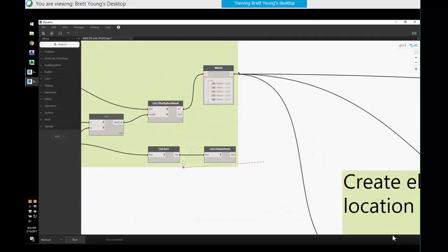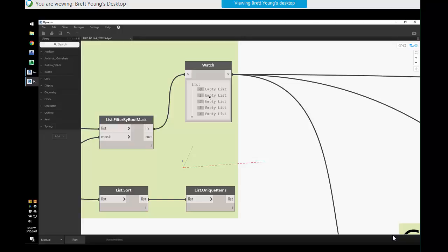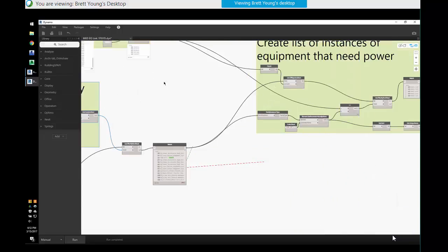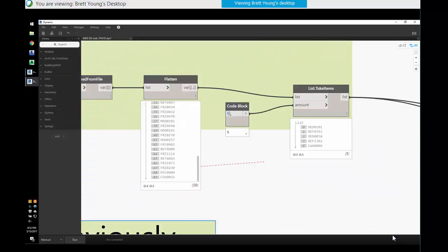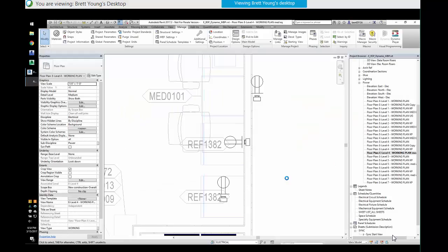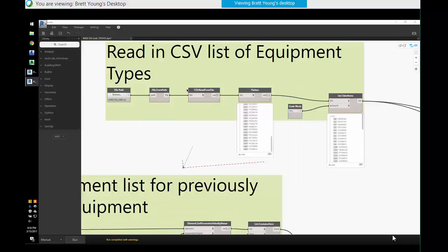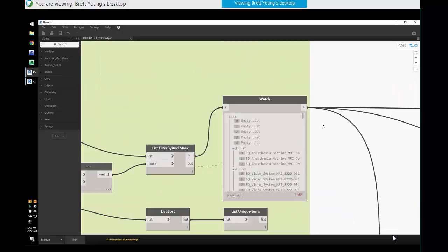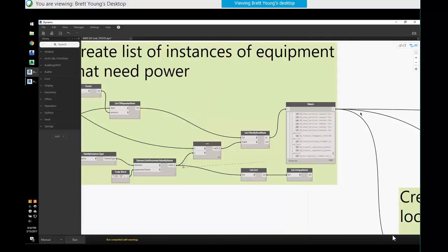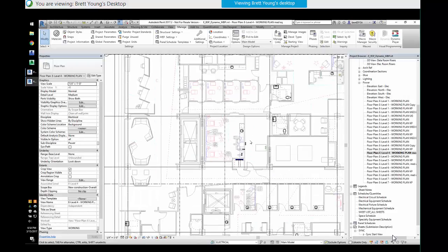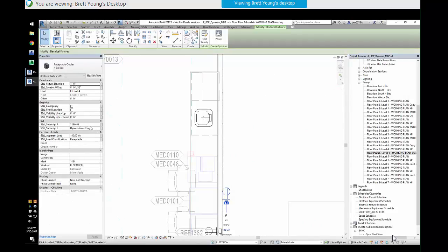So at the end of the day, I didn't put any more receptacles in round 2 because those first 5 pieces of equipment are already placed. So if I go from 5 pieces of equipment to 50, the full list, it's going to run. The first 5 are already placed, but you can run this every day to make sure that your receptacles are always matched up with a piece of equipment. So the second time around, the first 5 are empty, but now we have 142 extra receptacles I just got placed all over the place, and they have the device ID of the host piece of equipment, and they have this little special flag that I put in there in case I want to delete them all in a group.